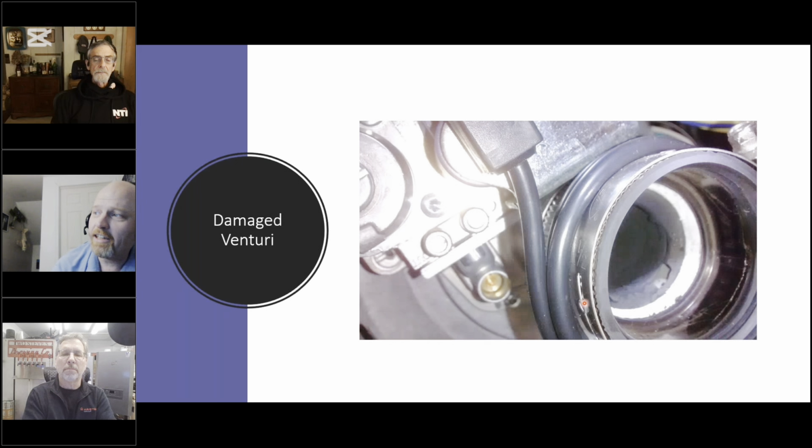Okay, and this is the last slide, guys. This is just a picture of a damaged venturi. It's the best photo I could find, but if you look inside here, you'll see the inner lip of the venturi where my cursor is, and you'll see it's all chipped and broken away. And the complaint here is that you could no longer set combustion on this boiler.